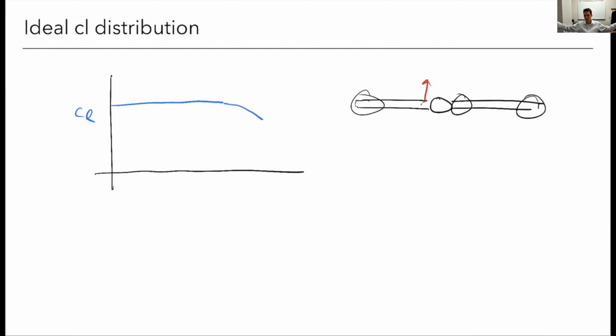This is actually probably a worse problem than the tip stall: if I don't have ailerons, they're ineffective because I'm stalling, then I'm losing that roll control. So I want to make sure that my lift coefficient is dropping out there towards the tip where my ailerons are going to be. All right, so I'm going to show you this complicated figure, and it's going to take you a while to unpack this. So this is in the book. I'm going to have you refer to look at it, but we're just going to go through it pretty quickly, and you can think about it more later.